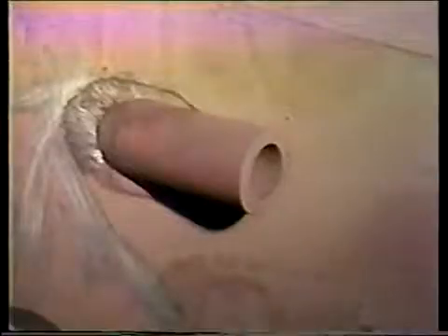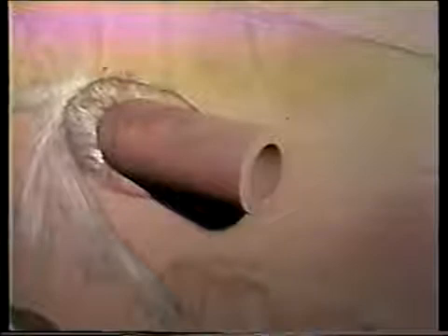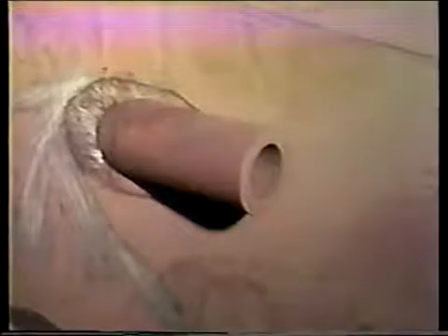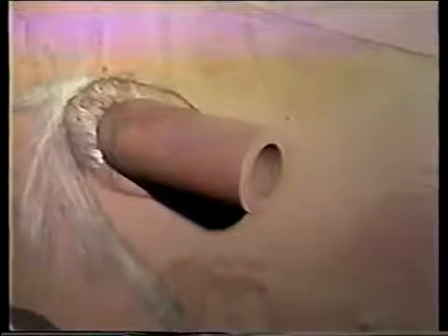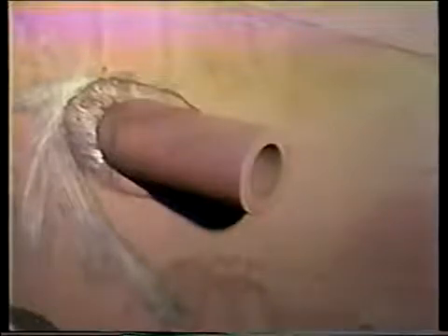Nozzles are found in all boilers. They're short pieces of pipe welded to a drum or header. This is a nozzle on the inside of a drum. Nozzles penetrate the walls of the waterside components and connect to boiler instruments on the outside. Nozzles also connect the drum or header to vents, drains, and safety valves, and those connections must be checked for damage.